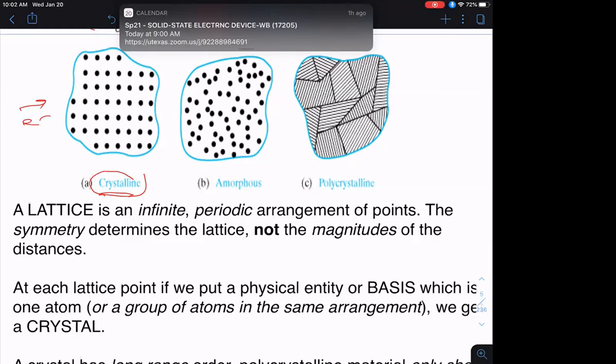On the other hand, if these atoms don't have any periodicity in space, they sort of put in random order, that's called an amorphous solid. So now if I try to move electron in there, we'll discuss this in detail in chapter 3 and 4. But hopefully intuitively you can see that the electron or the hole motion would be impeded a lot more. Therefore, the electronic properties would be inferior. Okay. Now, somewhere in between, you have what are called polycrystalline solids.